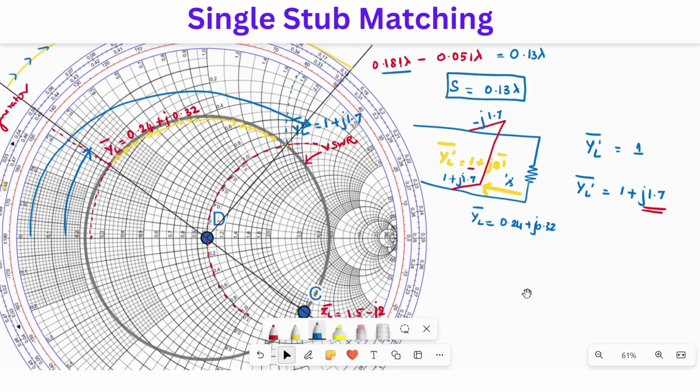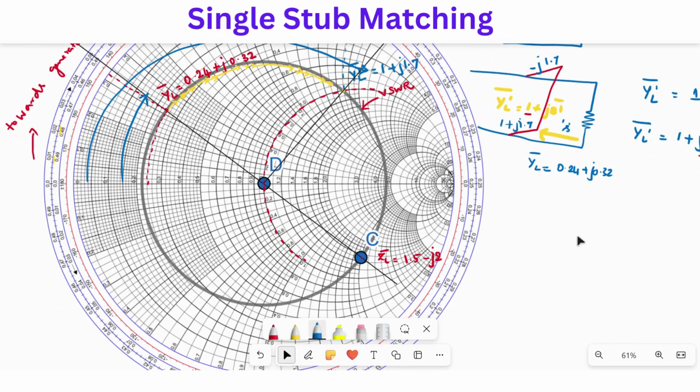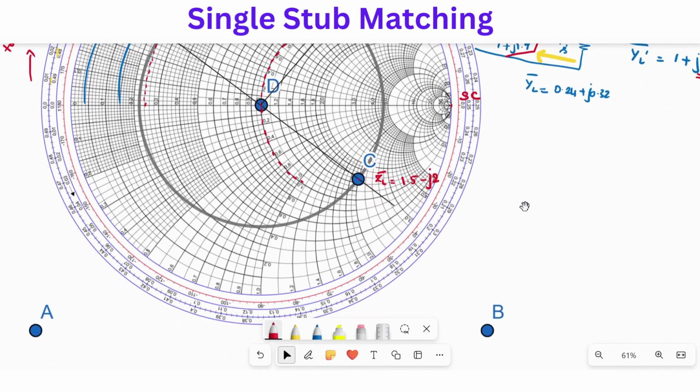And the stub is short circuited. So I'll mark the short circuited point right here. This point represents the short circuited point. And minus J 1.7 is right here. Because the resistance part is 0, right? I'm marking the reactance on the outermost circle. That is, the real part is 0, we only have the reactance part.